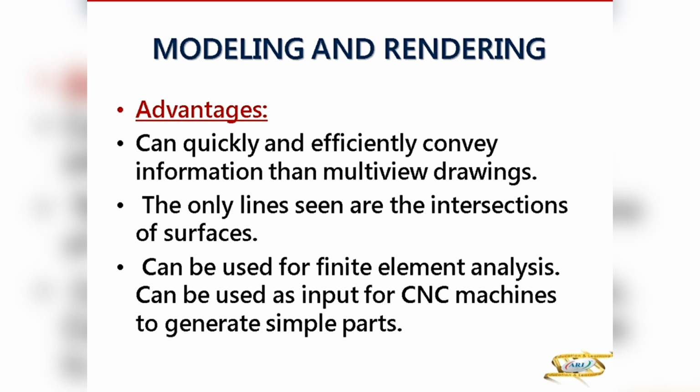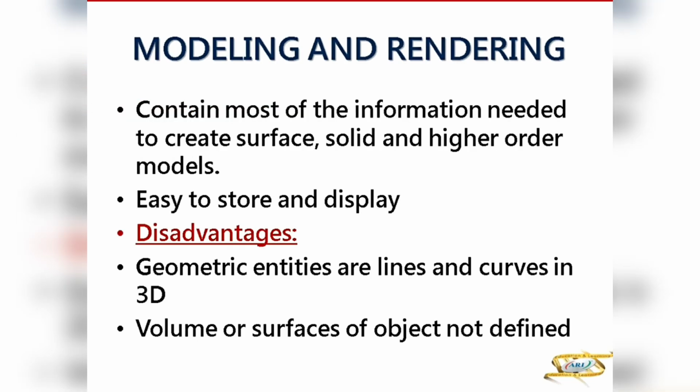You can have a multi-view drawing. You can have the lines as intersection of surfaces. So you can use it for finite element analysis. You can also input for CNC machines. And this becomes a basis for your surface modeling and solid modeling. Any higher order models are made from wireframe modeling.